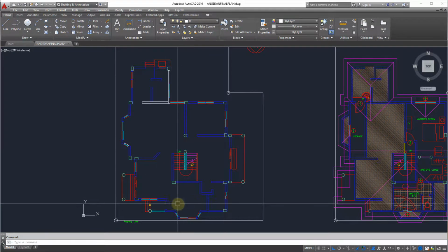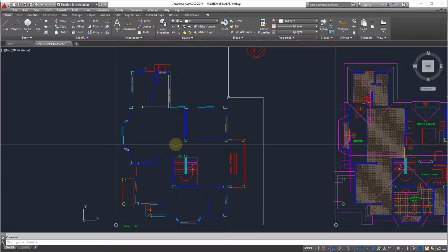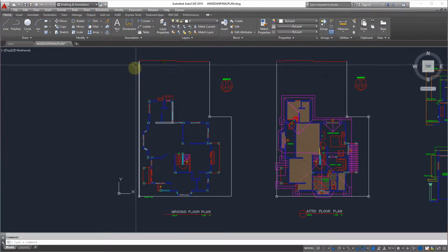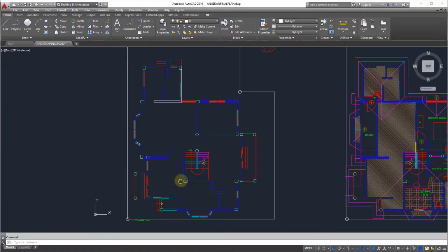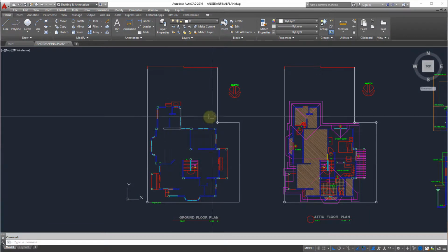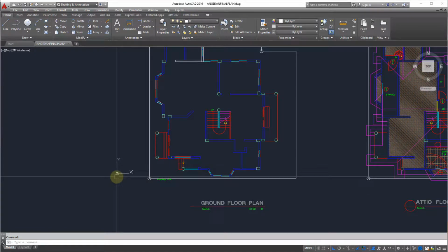drawings, like your furniture, toilet and bath pictures, everything. Retain only the ones that you need for creating your 3D models. For now we're going to focus on the exterior walls, the perimeter walls. So we need that part. And then once you're done with that, next we need to relocate your UCS icon.